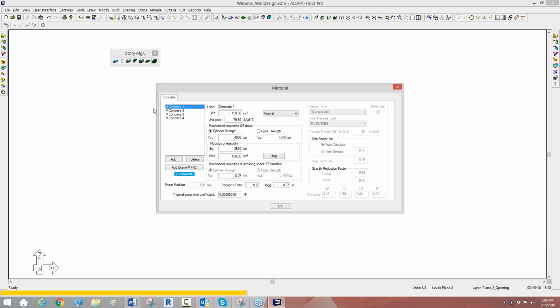So I'm going to leave the default concrete one as is. I'll just create this one. This will be 5,000, and then I'll do a 6 and a 7,000. And the reason I'm setting these up is just to show how they influence the design of the walls and how changes can be propagated when we go into the wall design process. So for 5,000, I'll change the compressive strength and the modulus. We'll do the same for 6,000 and the same for 7,000.